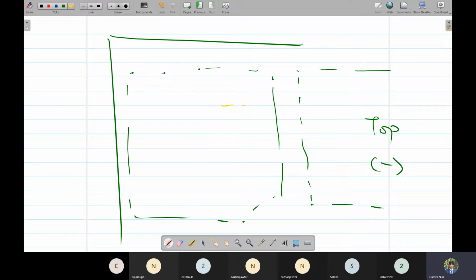This is negative steel in X direction. We are only providing steel at the support. You can say this length as L by 3 and this L by 4. Since this is Lx, so Lx by 3 parallel to the length. The other bar would be placed alternately.